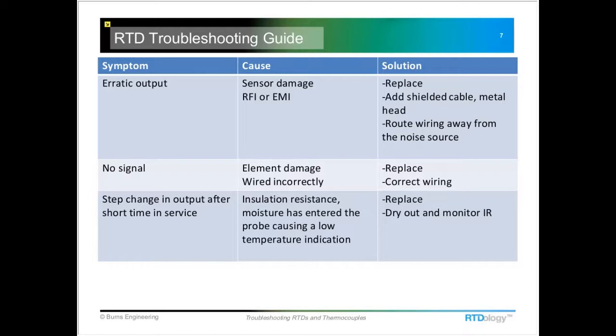You might see where the temperature was running along and all of a sudden it went open circuit or it spiked way up in temperature. That can be an indication of one of those internal lead wires is partially broken, and as the probe vibrates a little bit, it might be making contact and breaking apart, or just have some portion of breakage.